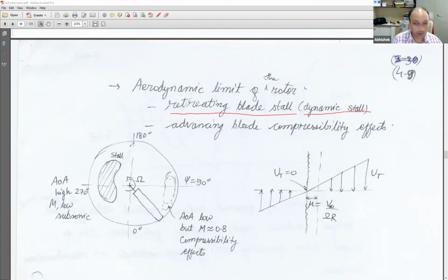And the way helicopter dynamics works, if I want my blade to go down here and go up here, I must decrease my lift here, so that this minimum lift here will cause minimum flapping here, because it's a second order system and my dynamics is such that the forcing and response delay is approximately 90 degrees.